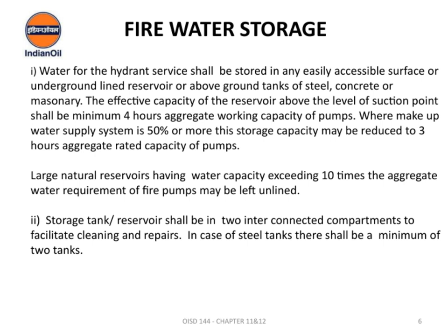Moving on to the design of storage tanks and reservoirs, they should be divided into 2 interconnected compartments. This setup makes cleaning and repairs much easier, and specifically for steel tanks, there should be at least 2 tanks to ensure redundancy and reliability. Overall, the main goal is to ensure a reliable water supply for fire protection, with proper capacity, accessibility, and maintainability built into the system.